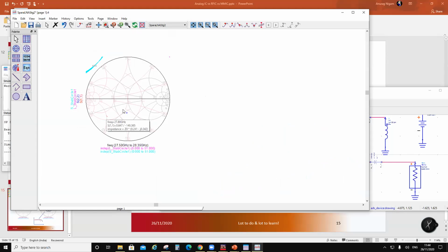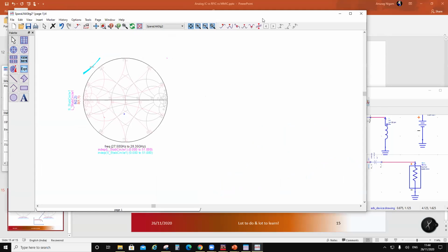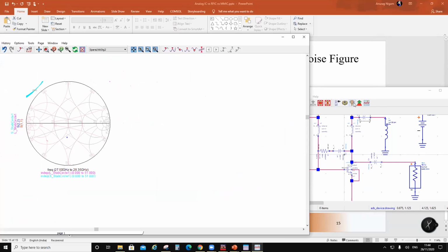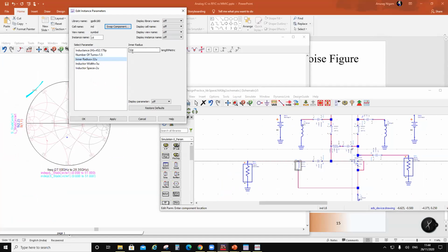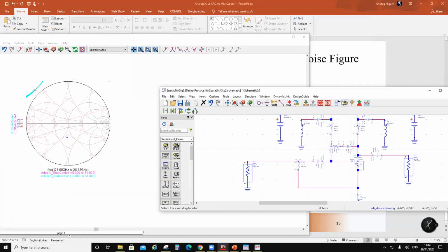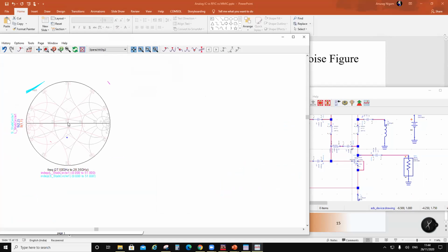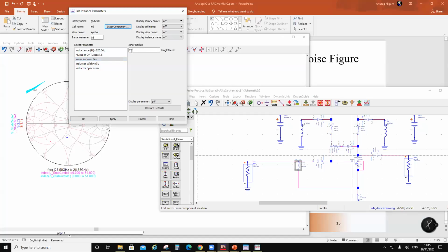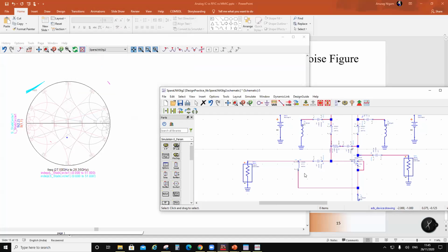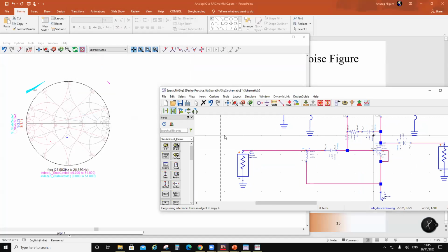Oh, we are over here. Okay. And how do I get over there? I would reduce this. And let's say I put this as 24 and simulate this. Okay, so this will move closer and closer. And 20 is the minimum size with 1.5 turns. Of course, this is the limitation of the process, but what you can do is put one inductor if you like. So I'm just going to copy this inductor and put it in parallel. Okay,